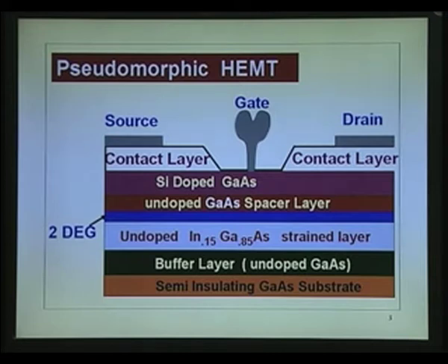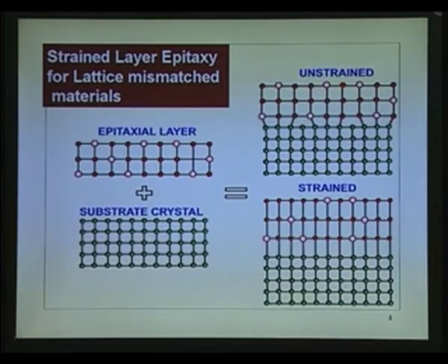Okay. When you say it is defect free, it does not have dislocations, etc. So, just let us take a look at the structure here. I will go back to the device afterwards. We are talking of now a layer which does not have lattice match, grown on a substrate layer. So, this is the substrate layer which has a certain lattice constant. It could be gallium arsenide or some lattice constant. Now, on the top of that you grow an epitaxial layer whose lattice constant is more than that of this.